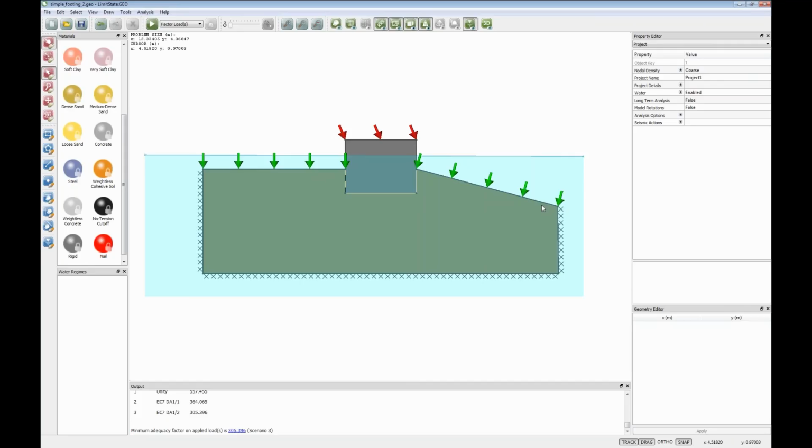favourable or unfavourable. I think generally Eurocode 7 tries to avoid this issue by pushing you towards design approach 1 combination 2 or design approach 3, where you factor favourable and unfavourable permanent loads by 1 in either case. So that kind of gets around the problem. If you need to factor them separately, then it's really up to you. You can split the problem up if you wish.